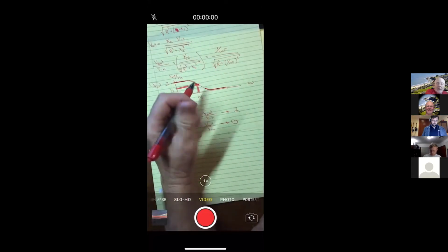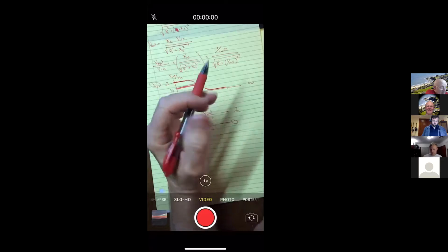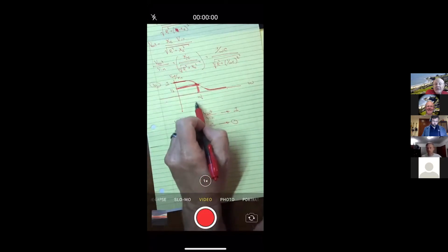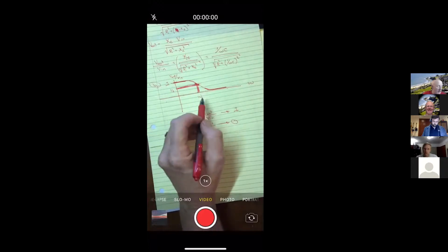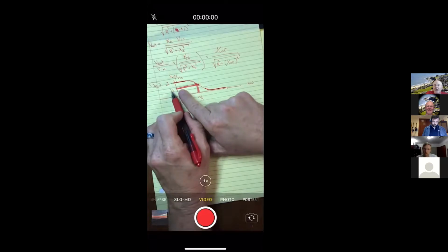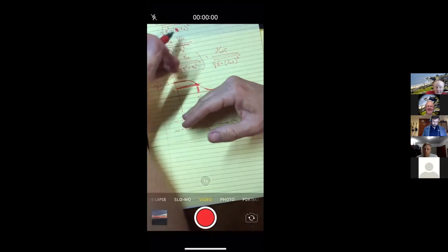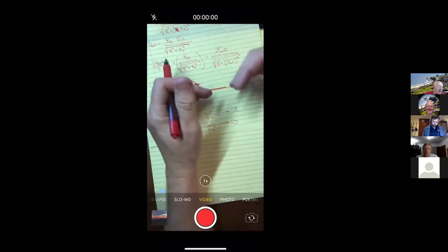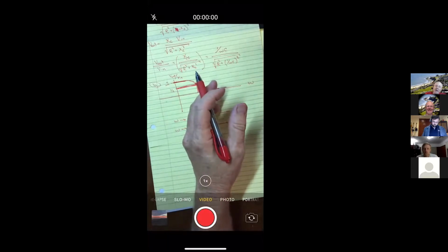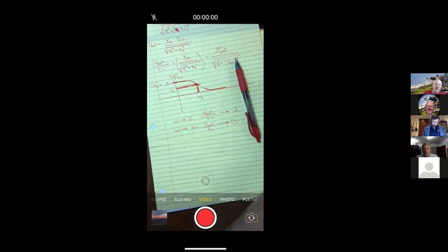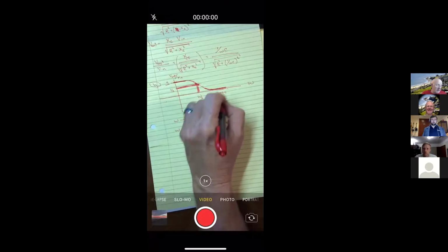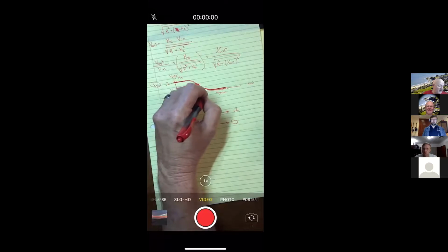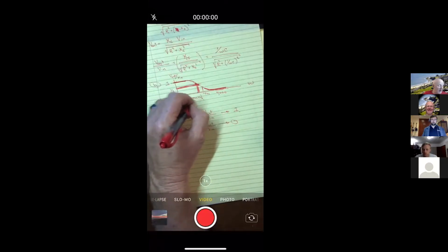And so a rule of thumb is we could rate this filter by that frequency. We could say this is a low pass filter at a frequency of, and I need to solve it, but let me just say 1,000 for a moment, meaning that all the frequencies below 1,000 are going to be at a half or stronger, and all the frequencies above 1,000 are going to be at a half or less. So this has a cutoff frequency of about 1,000. Things more than 1,000 don't get passed on very much. They still get passed on; in fact, the closer they are to 1,000, the more they get passed on. You can see it tapers off to 0. So something around 4,000 doesn't really get passed on, but something around 1,500 would get semi-passed on if this number here was 1,000.